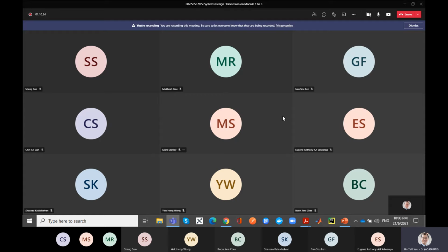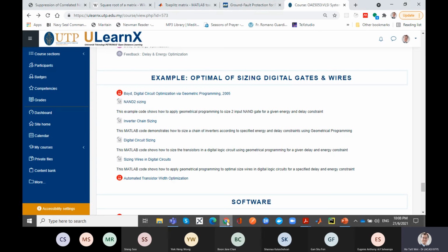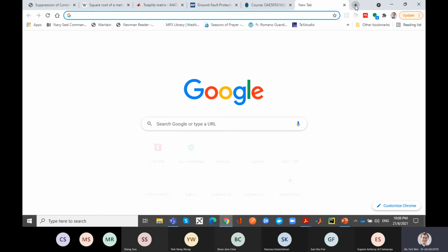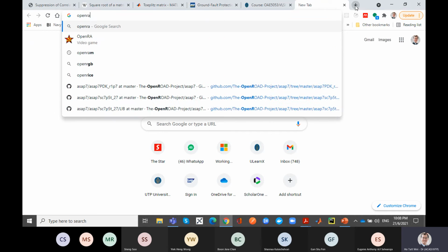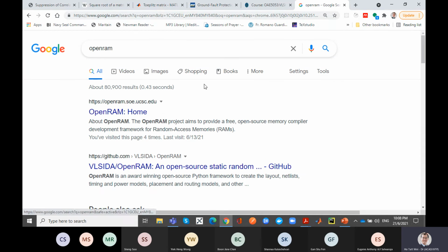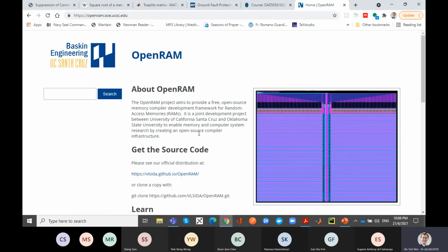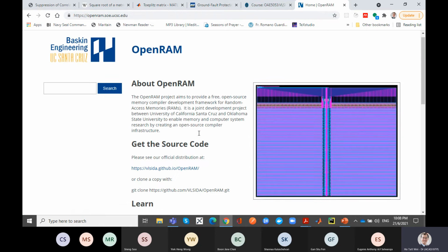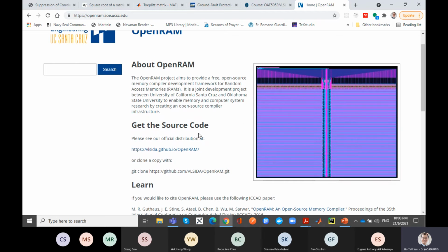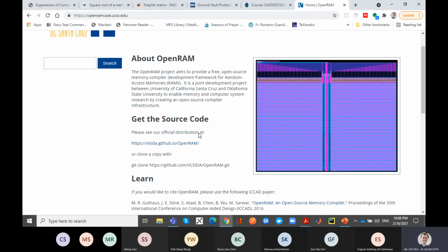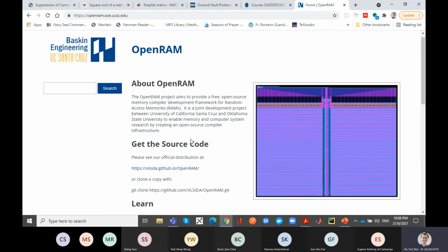So BJ, I'll take a chance here to respond to your question. Yes, the instruction cache and the data cache, you don't have to synthesize them. Most of your friends also don't. In fact, the instruction cache and data cache are a form of static RAM, static random access memory. They are not actually synthesized by RTL. Usually there's a separate path.